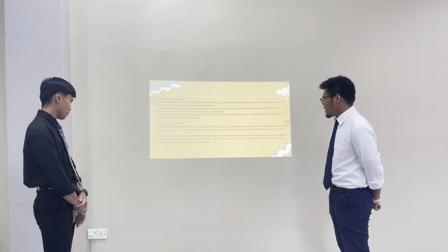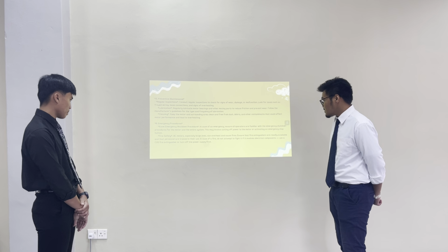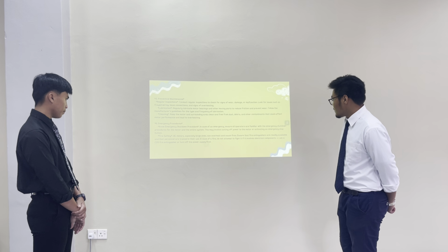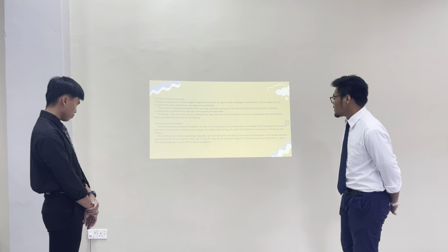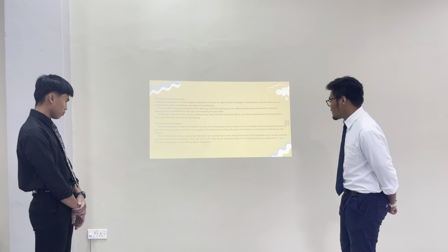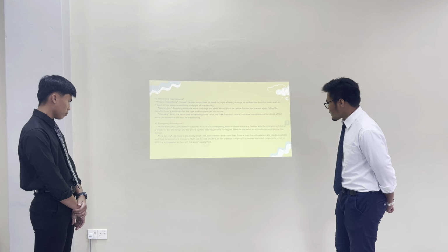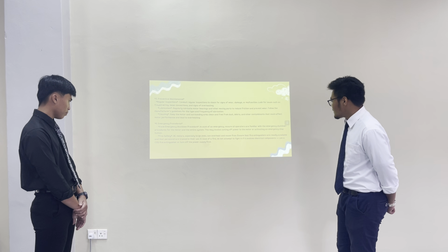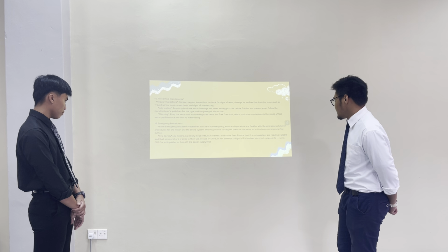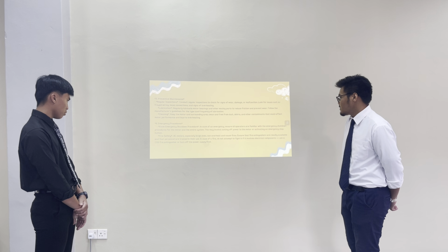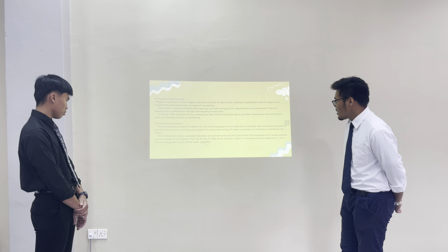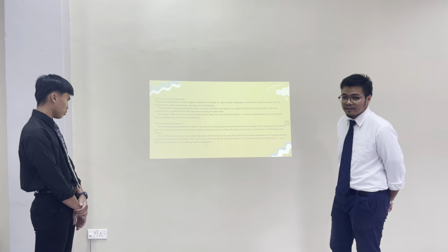Fire safety. AC motors, especially large ones, can overheat and cause fire. Ensure that fire extinguishers are readily available and that personnel are trained in their use. In case of a fire, do not attempt to fight it if it involves electrical components. Use a CO2 fire extinguisher or turn off the power supply first.